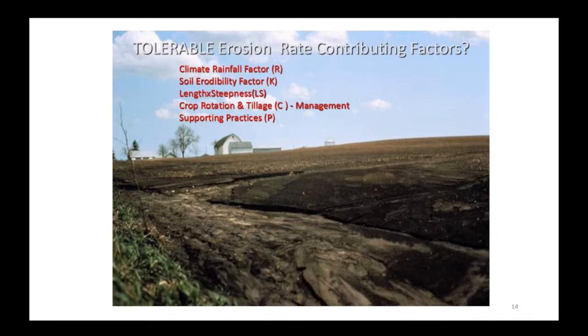Now, the length and steepness factor, referred to as the LS, kind of drives when we as planners select the most dominant critical soil. And the dominant critical soil directly relates to really how steep that mapping unit is, for the most part. There are some exceptions, however, a steep soil type, a mapping unit, really is going to result in excessive erosion if we do not have the practice in place to reduce the erosion.